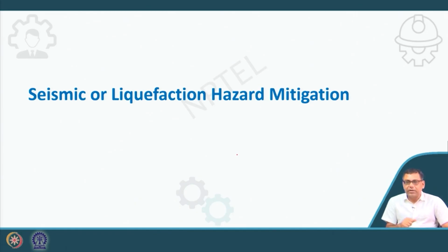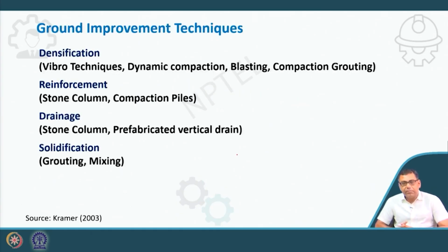So mostly I will go for ground improvement techniques to mitigate the seismic or liquefaction hazard, mostly liquefaction, because liquefaction is the major problem in geotechnical earthquake engineering.